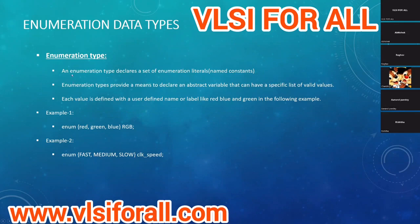So an enumeration data type declares a set of enumeration literals. In place of writing 000, we just say red, but the simulator knows red is equal to 000, and we don't have to care about it. We just focus on the intent.